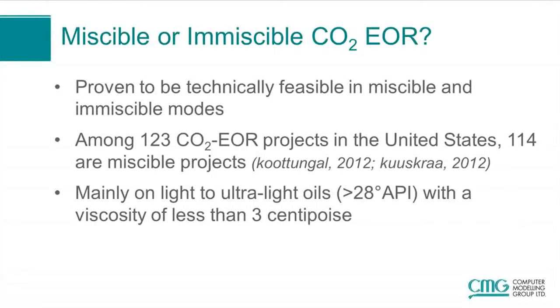Not all reservoirs are suitable for the carbon dioxide EOR process. Based on a simple screening, reservoirs with light to ultra-light oils, with viscosity less than 3 centipoise, are the reservoirs suitable for carbon dioxide injection.